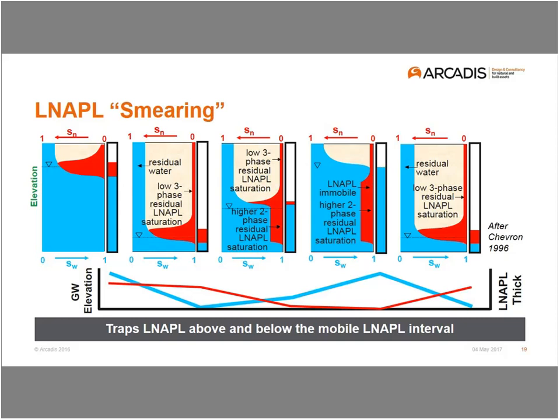But then if the water table drops again, we can remobilize some of this LNAPL. And we see that in droughts. I've seen that out here in Southern California, and I saw that the last few years with the drought out here. Got lots of calls, people saying, hey, we've got a site, we've never seen LNAPL for years and years, and suddenly there's some new LNAPL. Well, that's because our water table was dropping and exposing these submerged zones. So now we're seeing LNAPL in wells again.